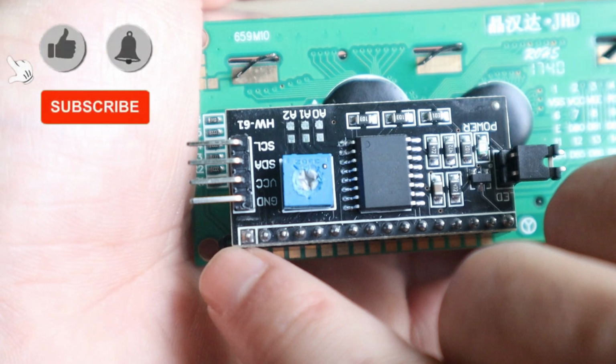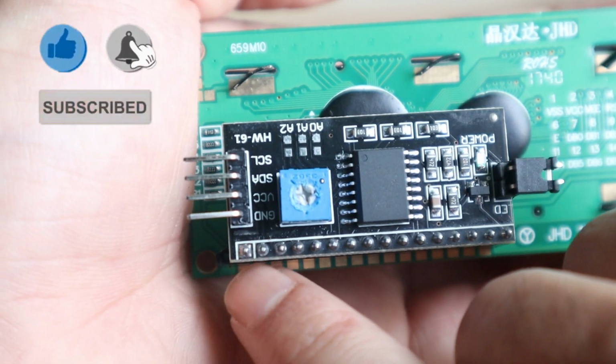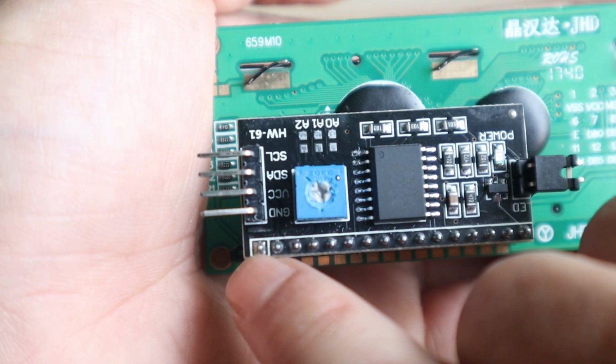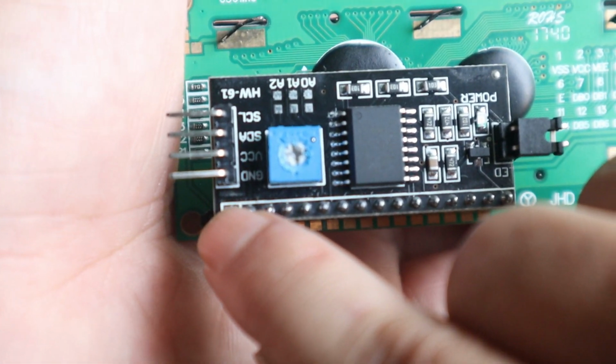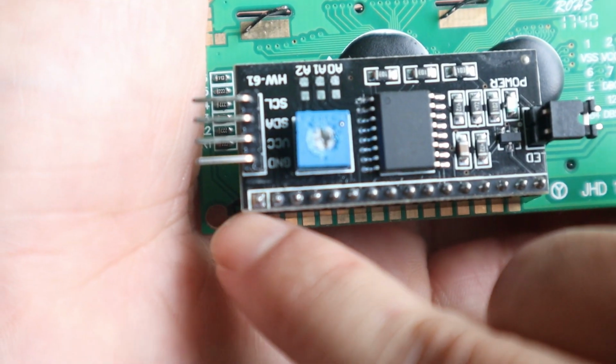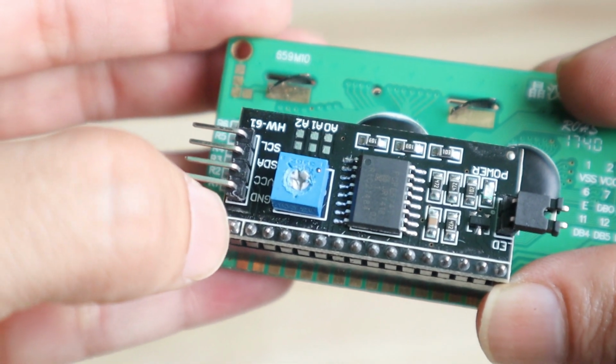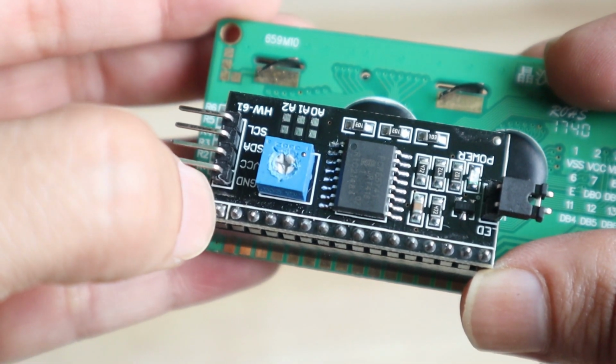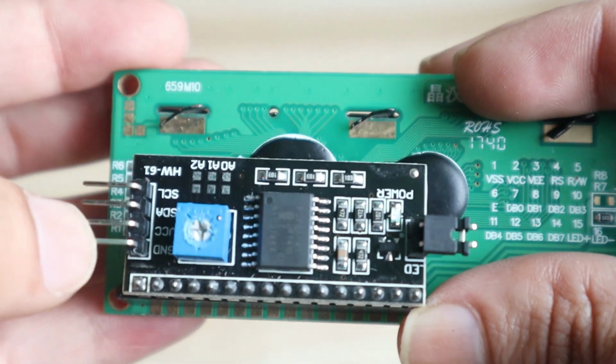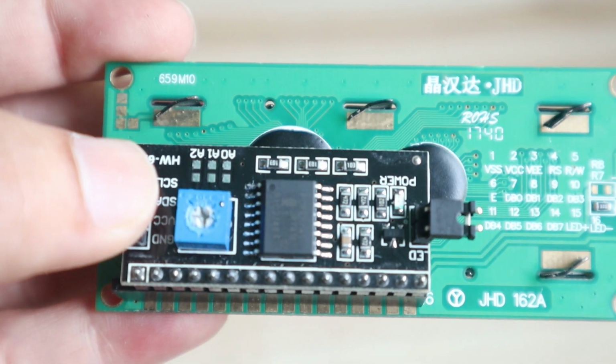Another way you can remember this pin connection, how to connect, is very easy. You can see there is a square box on this I2C module, on the first pin. So this is the first pin of the I2C module, and your LCD first pin should be connected to this square box. This is my LCD first pin. So the LCD first pin should be connected to the square box pin of the I2C module. That is very easy to remember, so you can also follow this.